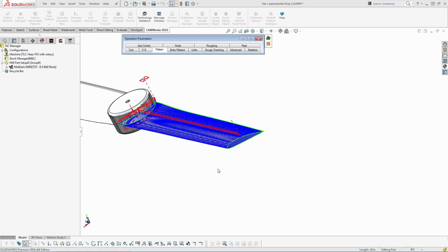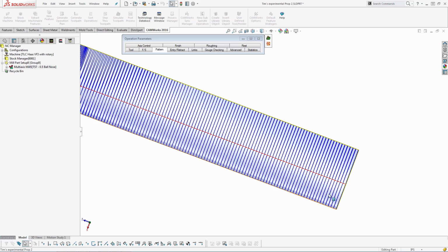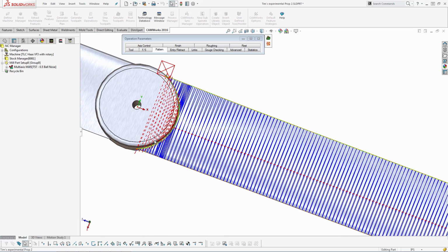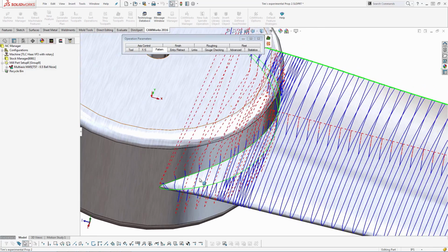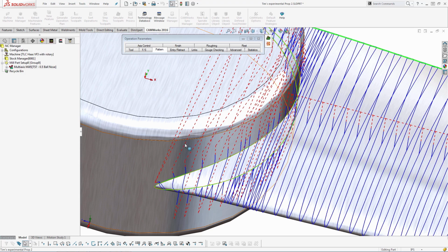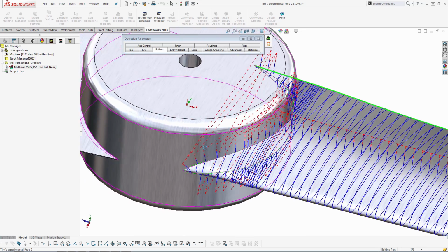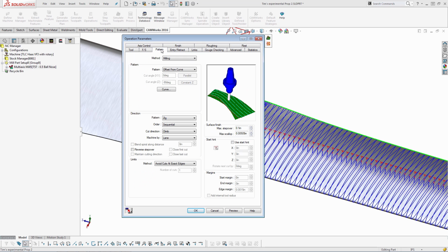we let this process and we can see it's offset. This is a straight line, so it's not that interesting in offset, but notice over here, it continues to be straight. We don't actually cut into this. We do gouge it a little bit. We can get around that. For this reason is why I probably wouldn't want offset curve. Now there's methods around this, but offset curve is just trying to make it work is probably not what we want to do.